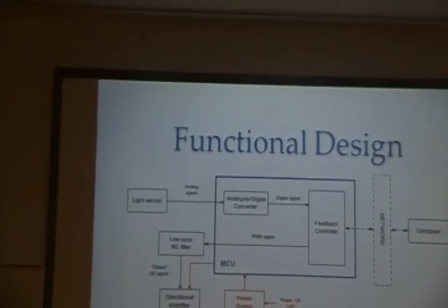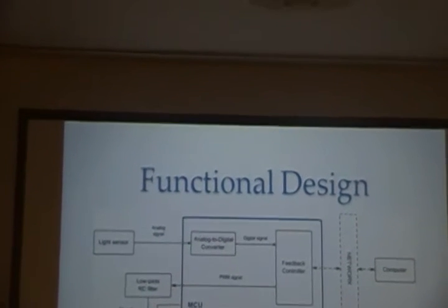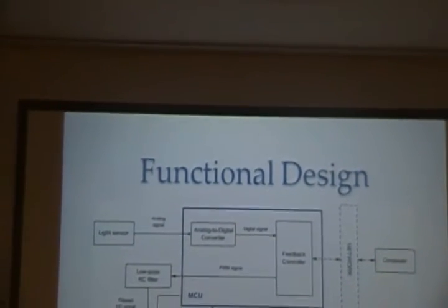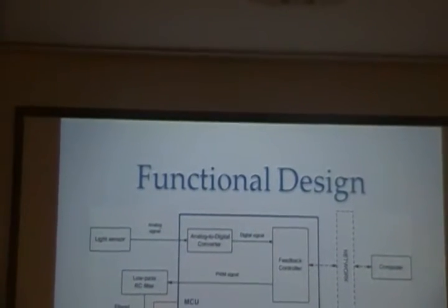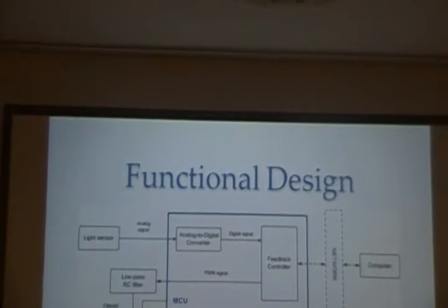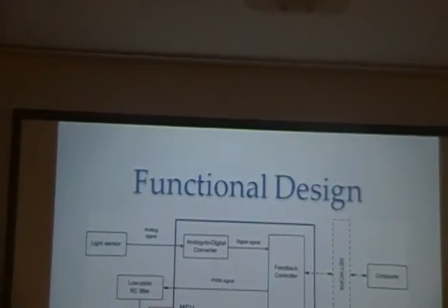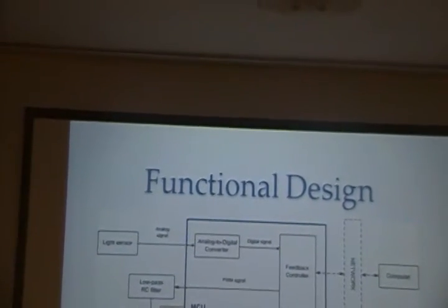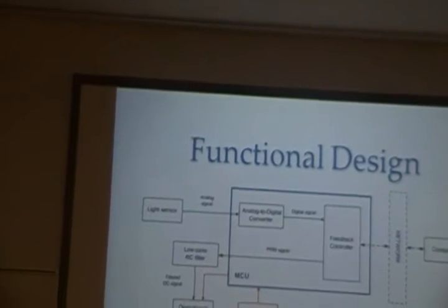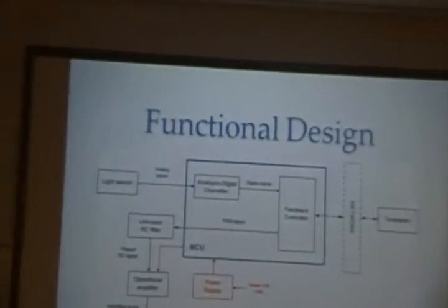The controller then outputs another value to an output port, which produces a pulse width modulated signal that has to be first filtered and then amplified before being sent to the electronic ballast, which regulates the current flow in a fluorescent bulb. The components I just mentioned, minus the sensor, the ballast, and bulb, make up what we call the local control system.